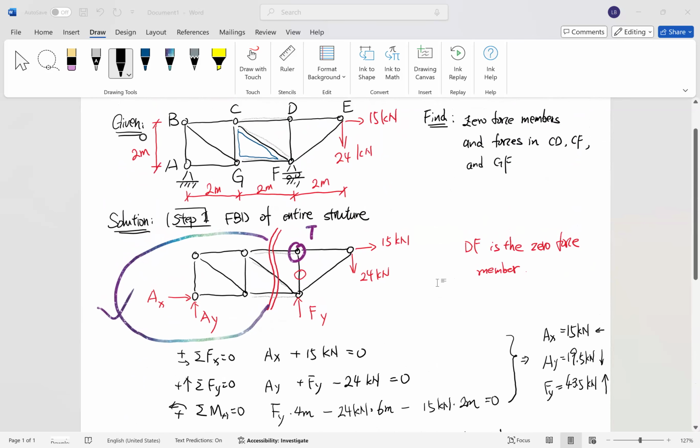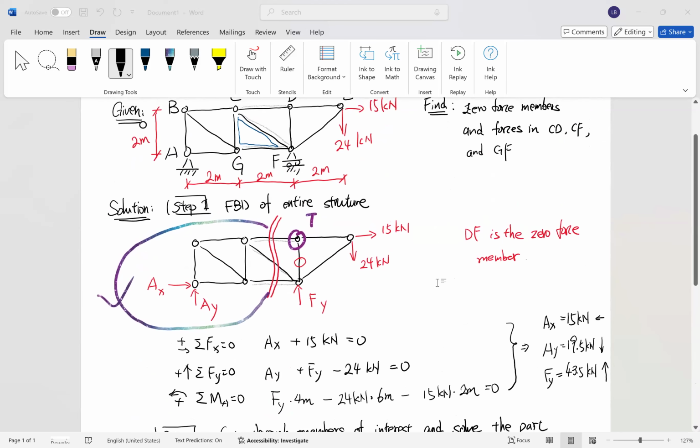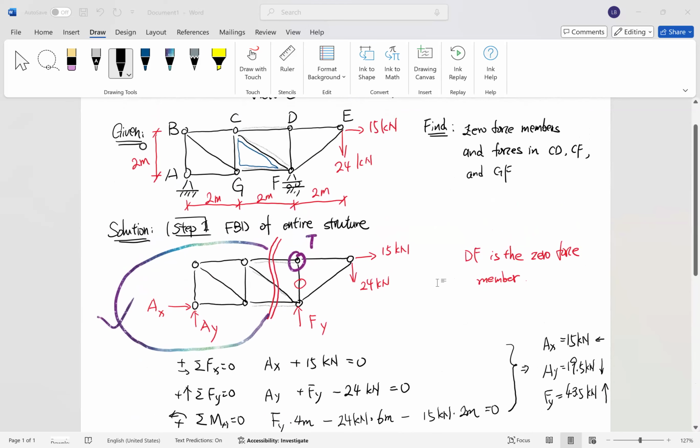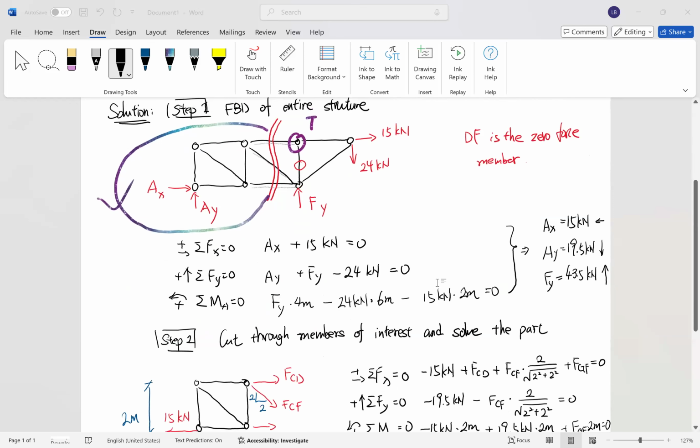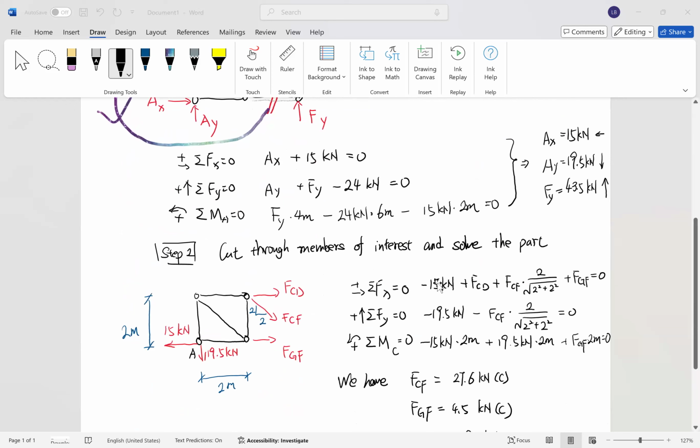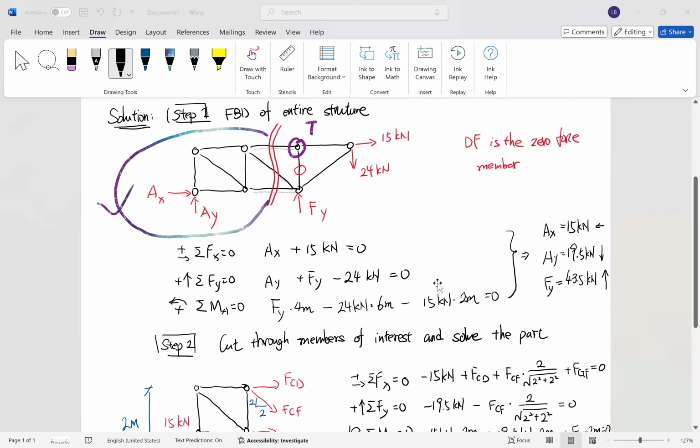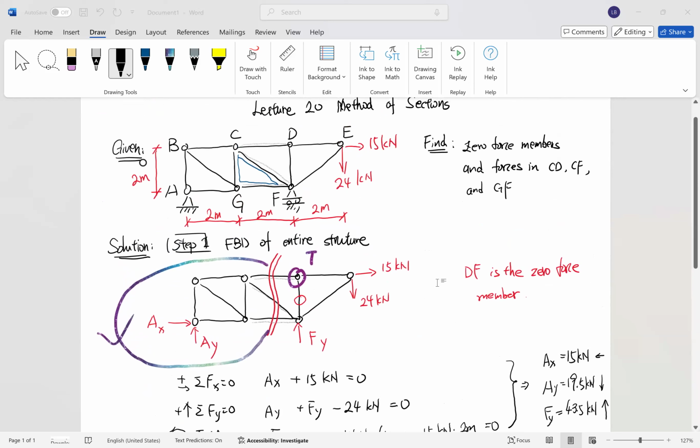Okay, immediately you are going to have all the unknown forces that you needed here. And sometimes in addition, we probably need to find some more members. In that case, either the method of section or further method of joint for some joints around may be needed. Okay, now here is one thing that's pretty important. When you cut through the structure, you expose unknown forces. At once, how many unknown forces can we expose and address?